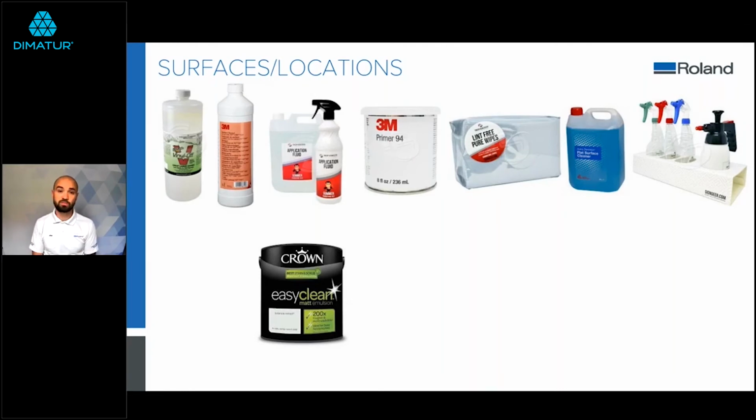If you've got a portion of your materials, maybe send that to the customer or apply that a week or so before you're going to be applying your graphic, and check whether it's going to peel off from the wall. You would want paints to probably cure or fully dry. It depends on the different type of paint, but probably around 30 days before applying your graphic. It does depend on the type of paint, but the only way to really know is to do a test. So just make sure that when you're talking to your customers about this, that you again manage their expectations on the adhesive type of your material.